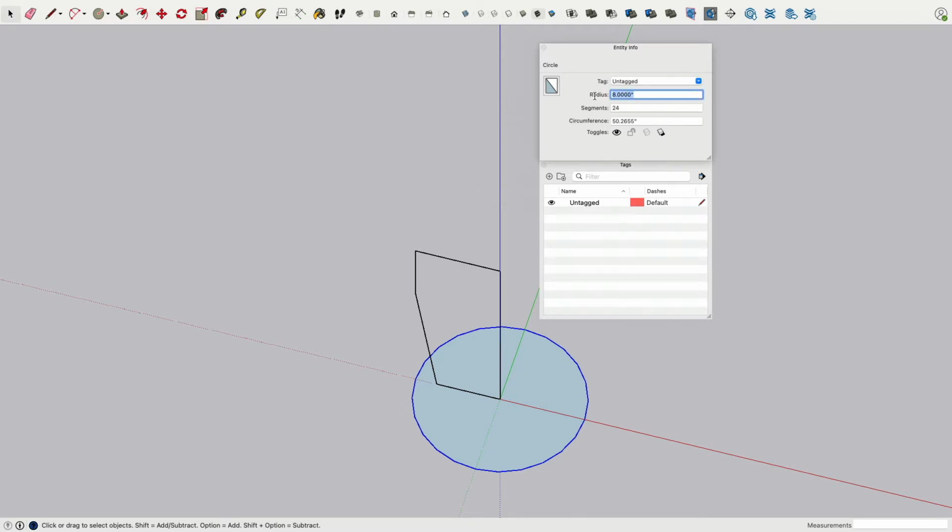Here we can now override everything. 6 inches, 7 inches, 8 inches. And segments, what's that? Take a look at this, 10 segments. And you see, it actually gets more or less faceted. For even crazy 32 or 40, 64. These are like good numbers. 24 is like one version, 32, 48. This is really all up to you. I will go with 32 for the moment.